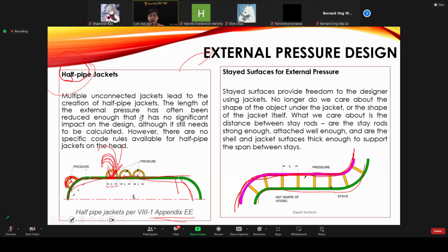Okay, so now you want to remove or supply the heat energy to the content inside the pressure vessel by using the jacket. Let's say this one is the jacket, the outer surface of the jacket is here, the outer surface of the shell is here. Okay, in a common jacket the water will flow through the gap in order to supply or remove the energy. So in that case, we also need to make sure the thickness of the shell is strong enough to withstand the external pressure that can be found inside the gap here.